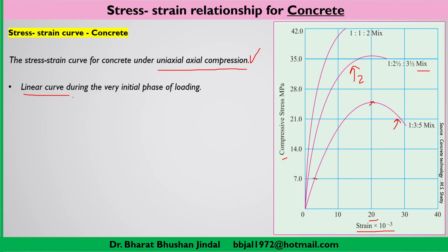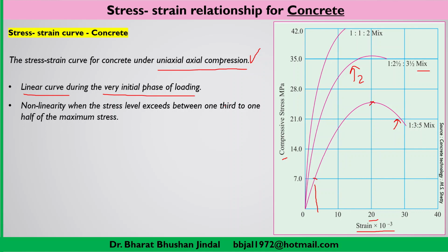So this is the linear part of the curve during the very initial phase of loading, where the strain is approximately 5 into 10 raised to power minus 3, and the corresponding stress is 7 MPa. Similarly, from this graph we can analyze that when the strength of the concrete is increasing, the relationship is changing. Now, let us talk about the non-linear portion.